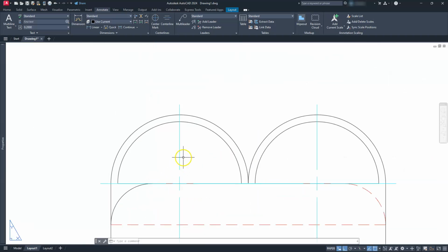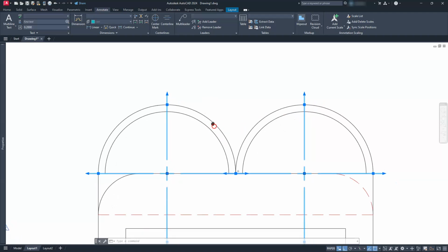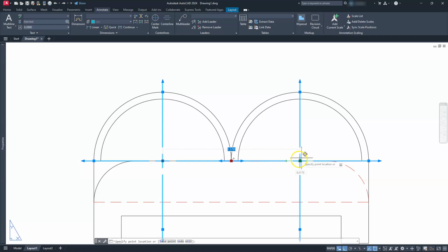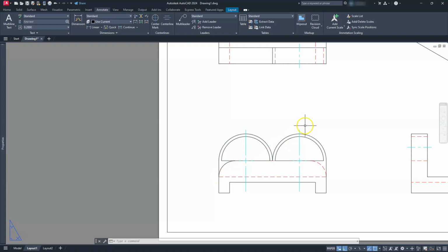And then here, we're just going to go ahead and shorten both of these up. So I'll select that center mark here, and then this one. And remember that we're just trying to put these centers on top of each other. And it looks like when I did that, I actually grabbed both of them. Okay, that's what I wanted to happen. So I'm going to place that one onto this one. Let's take a look at here. And there's nothing wrong if you did leave these the way that they are. It's just me, I kind of like to get rid of that stuff and make sure that it's nice and clean on my drawing. So let's go ahead and select both of these center lines again.